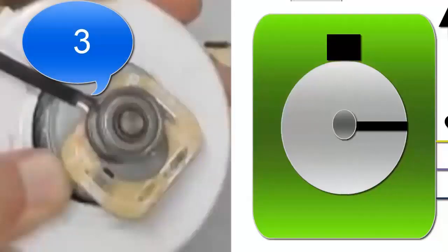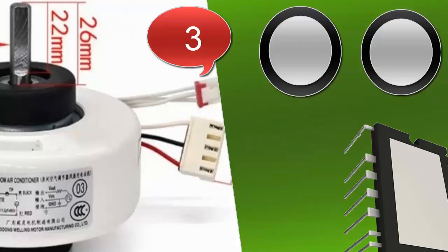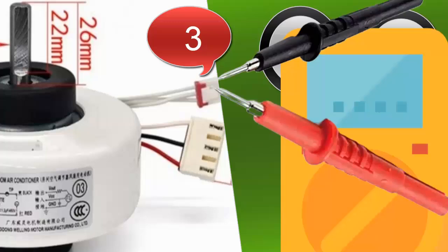The fan's Hall effect sensor generally uses 3 thin wires, finer than the power cables of the fan motor. These 3 wires correspond to the power supply, ground, and output signal. In most cases, the sensor operates with a 5V power supply.